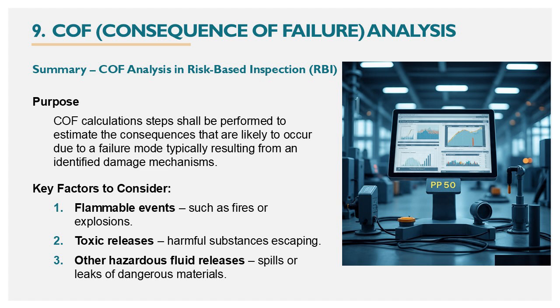COF calculation steps shall be performed to estimate the consequences that are likely to occur due to a failure mode typically resulting from an identified damage mechanisms. Key factors of COF analysis to consider includes, number 1, flammable events such as fires or explosions, number 2, toxic releases, harmful substances escaping, and number 3, other hazardous fluid releases, spills or leaks of dangerous materials.